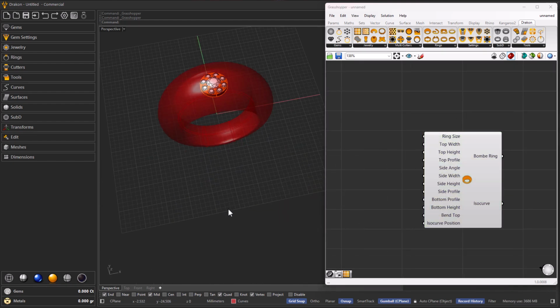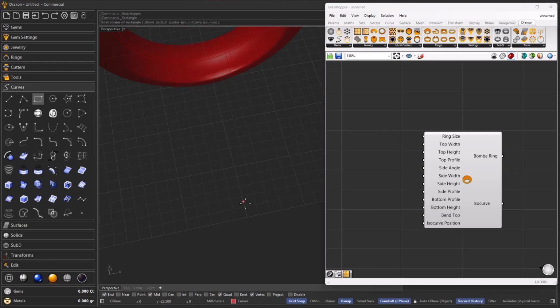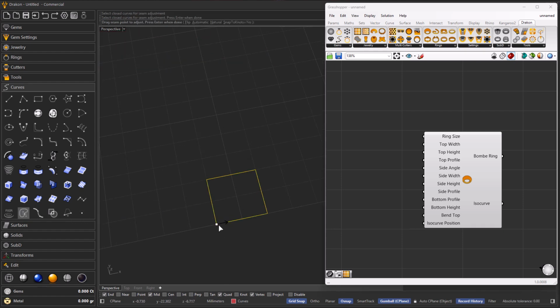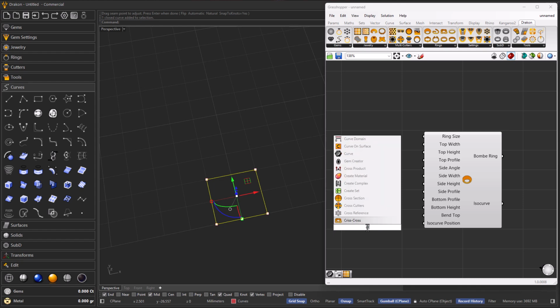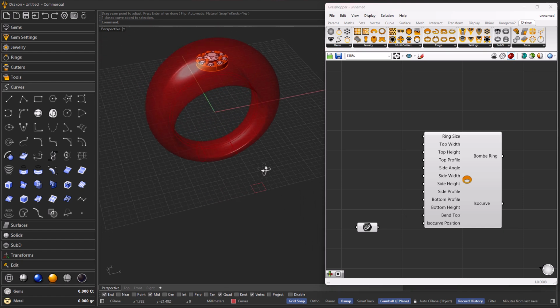And what I'm going to do at this stage is to create a profile. So I'm going to the curves menu directly on Rhino, and I can set the curve. Remember to adjust the seam into the middle. So I just select the seam, enter to be placed in the mirror, and I'm going to use a curve. Double click on curve and type curve. So I set the curve, this one, and once again I internalize data, which means that I don't need the Rhino geometry anymore. I can delete it.